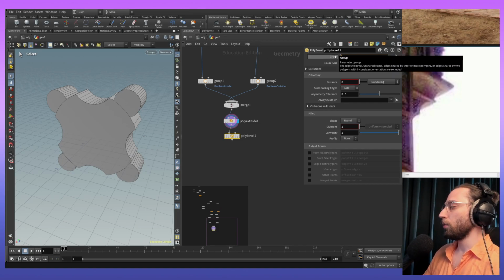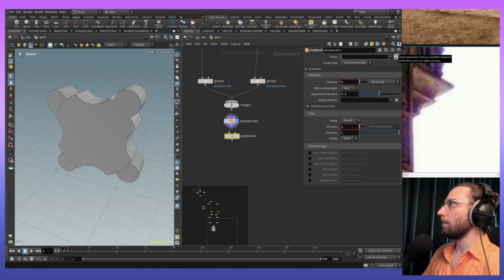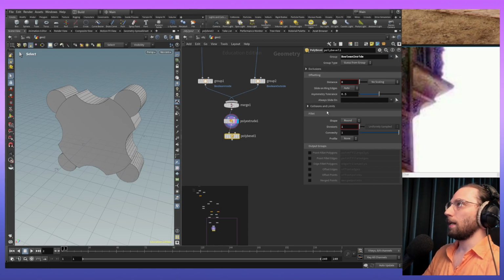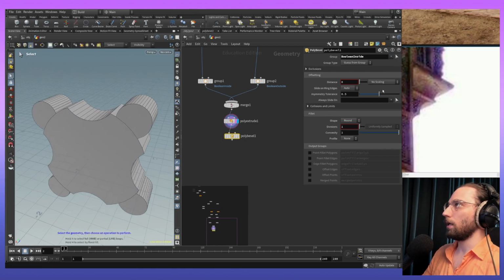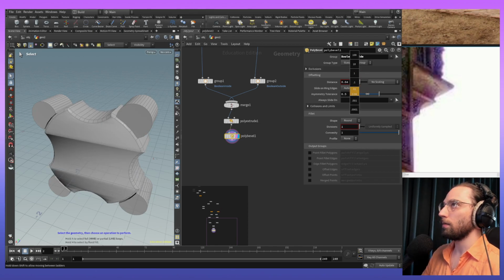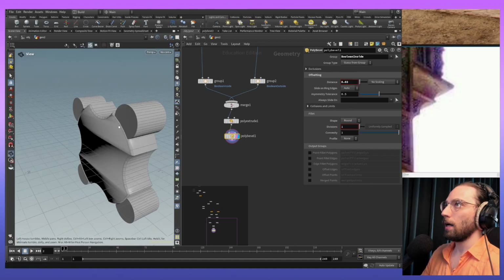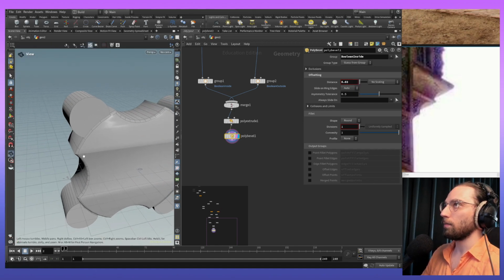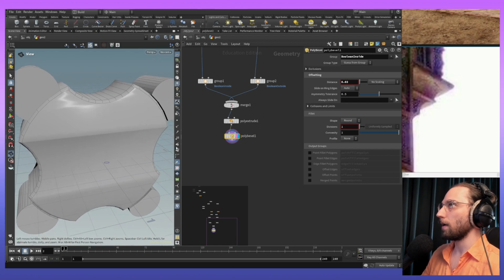So with the group, we can drop down and say we only want this to happen on the Boolean inside, for example. And now we could add the Boolean the bevel value, which could be added from here. That's too much, of course, 0.1, like this, for example. And so now we're adding on the different booleans that we have. We're adding the values that we want to add.